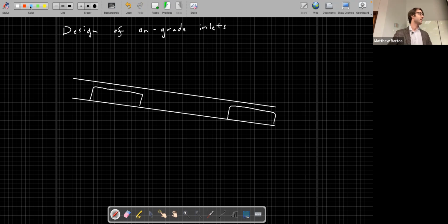Okay. And along our curb, we have some rainfall coming in. This might be rainfall, or it might be runoff from the surface, either from the roadway surface or from the surface above the curb. So I'll just call this W. And as this rainfall falls into our gutter, it's going to create some water surface. Will come up like this. And it will eventually get discharged into our curb inlet. Kind of the same thing is going to be happening here. Okay, and the flow in this portion we will call Q.